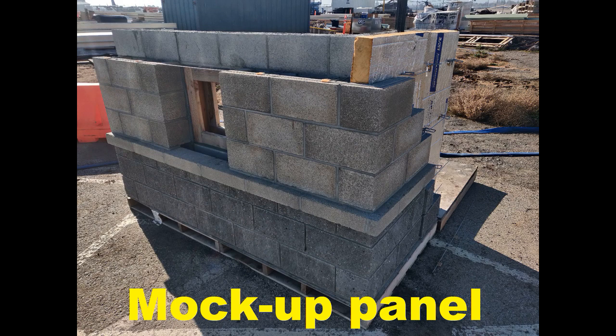Mock-up panel purpose. The completed panels are used as the standard of workmanship for the type of masonry represented. Do not commence masonry work until the mock-up panel for that type of masonry construction has been completed and approved. Protect panels from the weather and construction operations until the masonry work has been completed and approved.